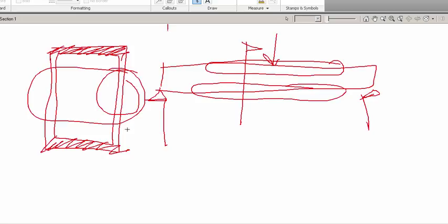So that's why W beams, or even C channels, work out better, because we may only need technically one wall to work with, so we could technically get rid of the other one and be fine structurally speaking. That's why C channels or W beams will typically be used more in a beam scenario.